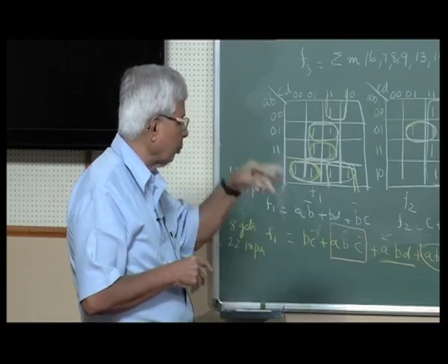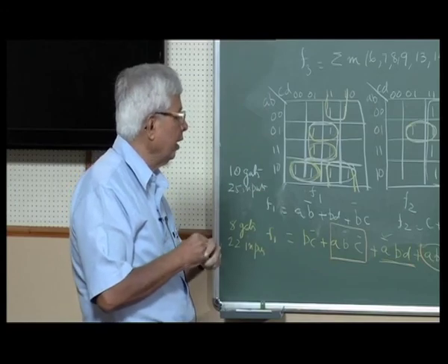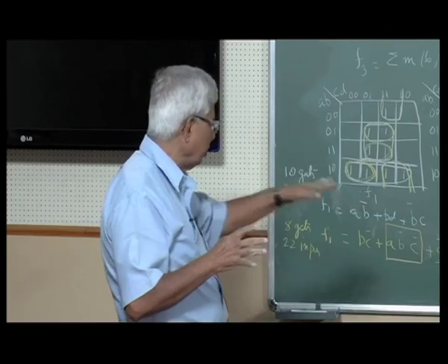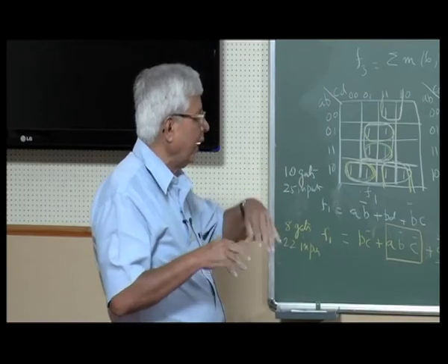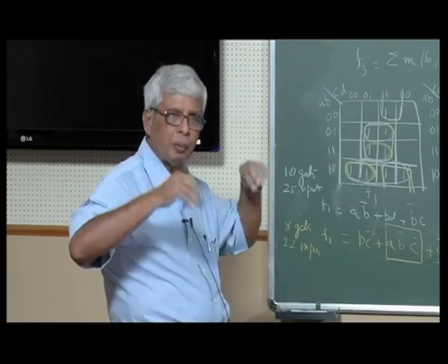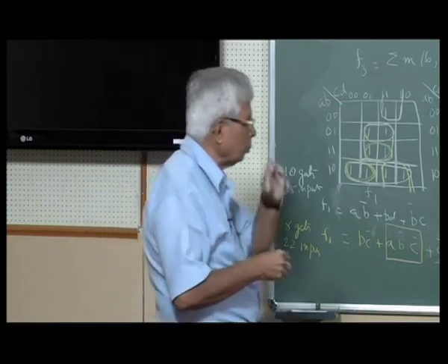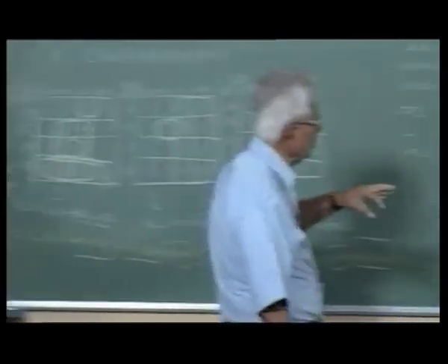So we go for the programmable logic array, where we write the functions, simplify them, make as many product terms as possible common, and only generate those product terms using AND gates, and then combine them with OR gates.